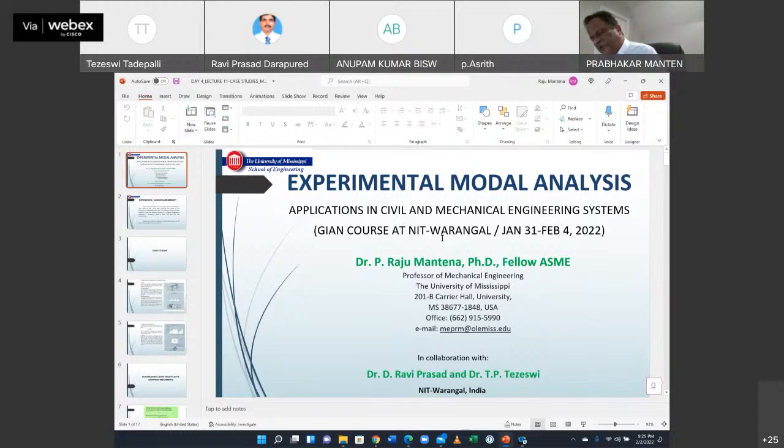Below that, usually under the table, they'll attach a smaller, lighter spring and a smaller mass element, which together turn the whole system into a two degree of freedom system instead of a single degree of freedom system. When the whole system is running, the fundamental mass and spring are moving up and down, and the secondary mass and spring will also start oscillating.